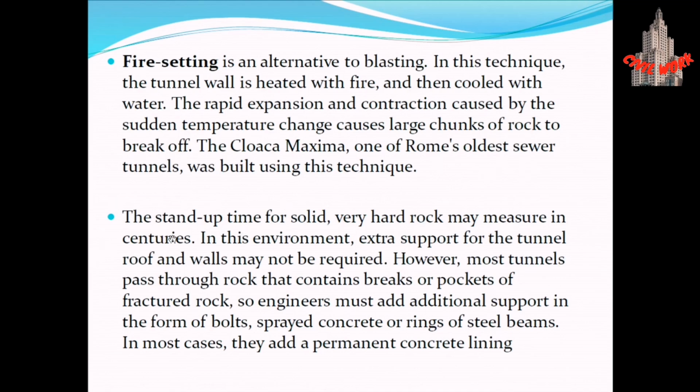The stand-up time for solid, very hard rock may be measured in centuries. In this environment, extra support for the tunnel roof and walls may not be required. However, most tunnels pass through rock that contains breaks or pockets of fractured rock, so engineers must add additional support in the form of bolts, sprayed concrete, or rings of steel beams. In most cases, they add a permanent concrete lining.